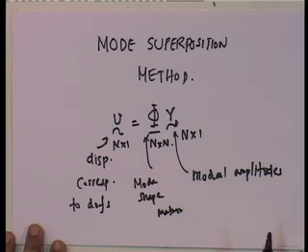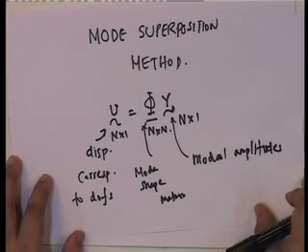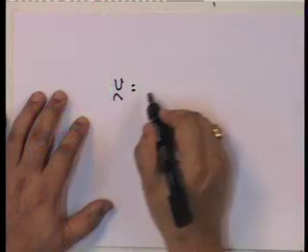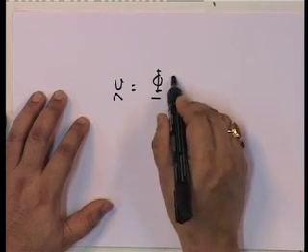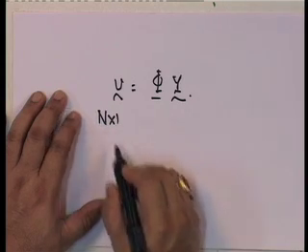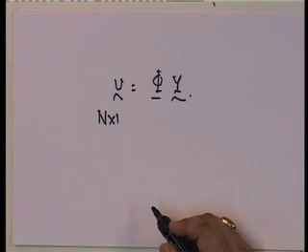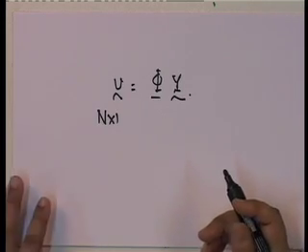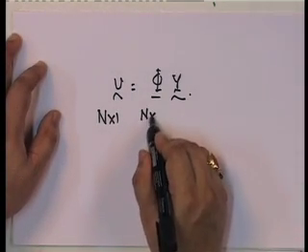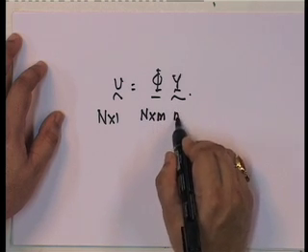Okay. Now, remember last time we said that in reality, you do not require all the modes to be considered. So V is equal to phi into y, where this is n into 1. This remains n into 1 purely because it is an n degree of freedom structure. So, these are displacements corresponding to each degree of freedom. This is no longer n by n, it is n by m.